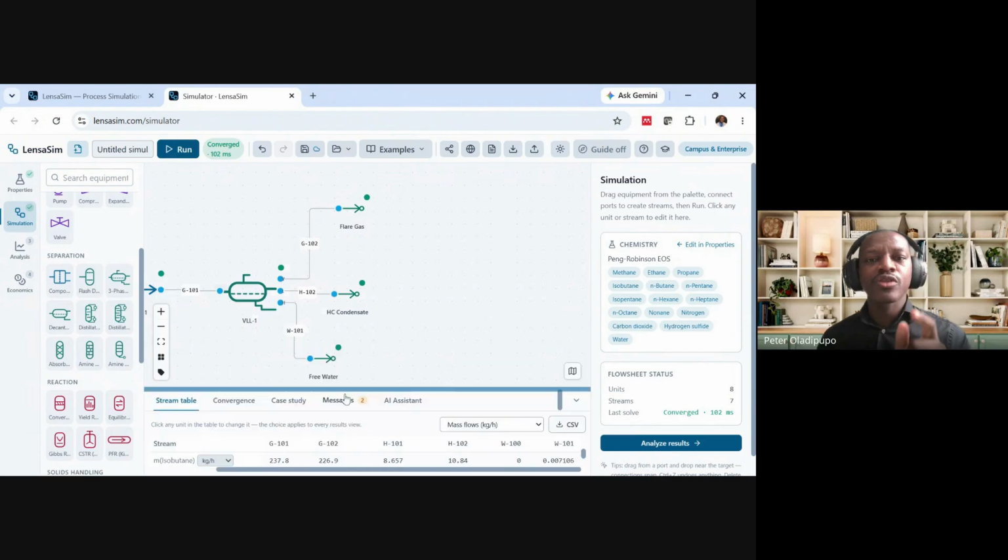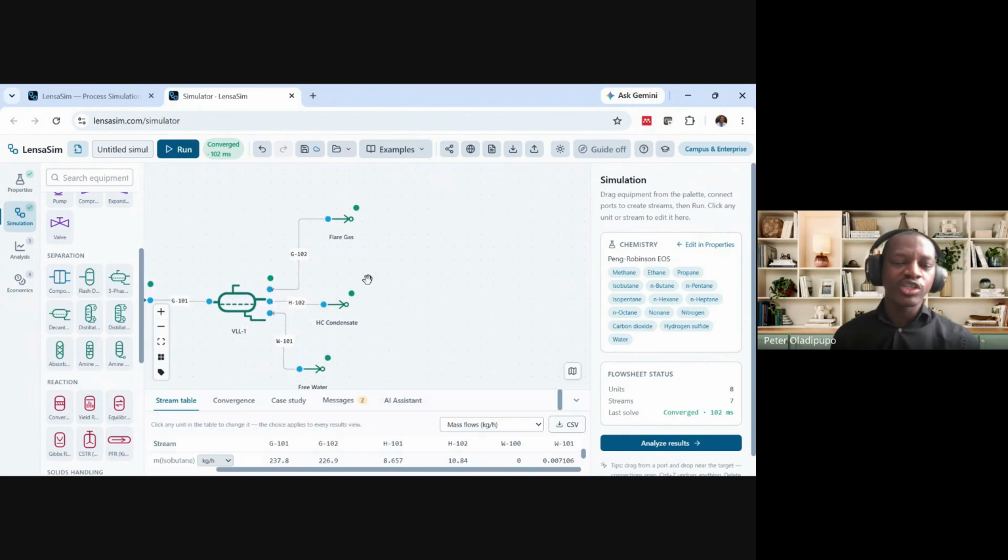First, we'll be removing the acid gases, CO2 and H2S. There's a specialized unit for doing this in the petrochemical industry. It's called the amine sweetening unit. It's an absorption tower, and you essentially send the liquid absorbent from the top of the column, and then feed the gas from the bottom of the column.